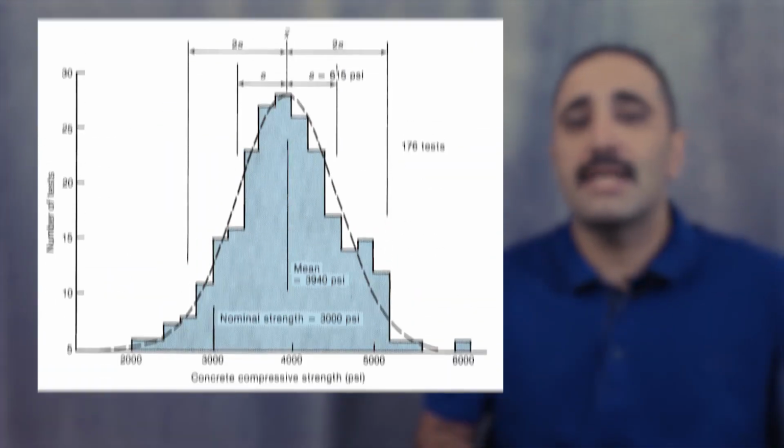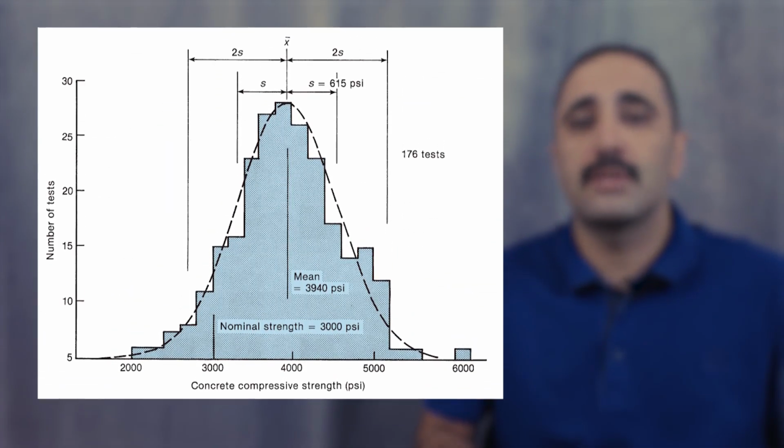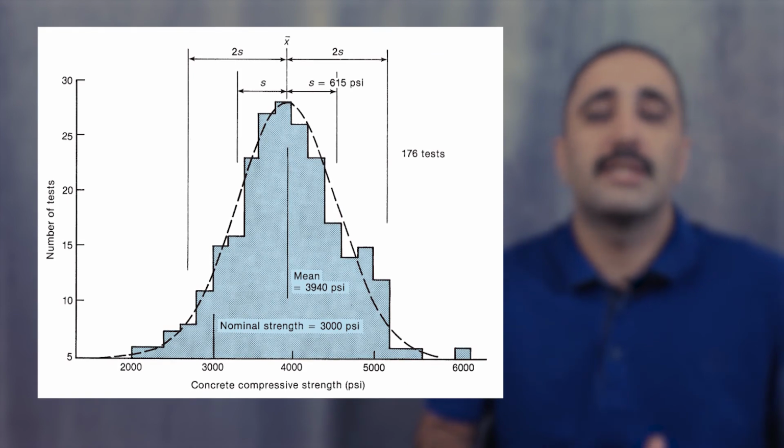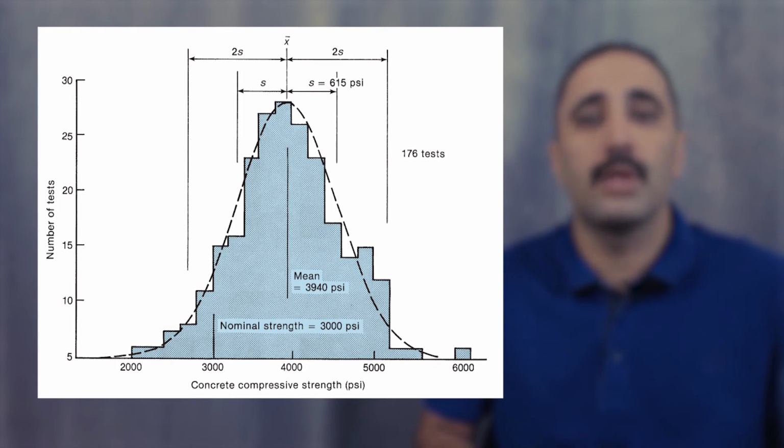Similar to most natural phenomena, the concrete strength follows a normal distribution. This means that if we aim for 4,000 psi compressive strength, it is possible that 50% of our test results fall below that target statistically. It is too clear that it is completely unacceptable for structural safety.